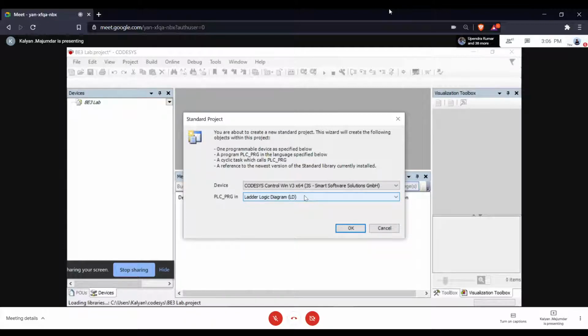You have something called FBD, function block diagram. This is very similar to what you were taught in your digital electronics class. There, whenever you draw a schematic diagram, you have symbols for all kinds of logic gates, right? Here we have something very simple. We have function blocks, which represent different functions. So instead of drawing symbols, you write blocks with AND written there, or XOR written there, or whatever, which represents a function. And then they're interconnected exactly the way you draw a schematic circuit in digital electronics. That's FBD, function block diagram.